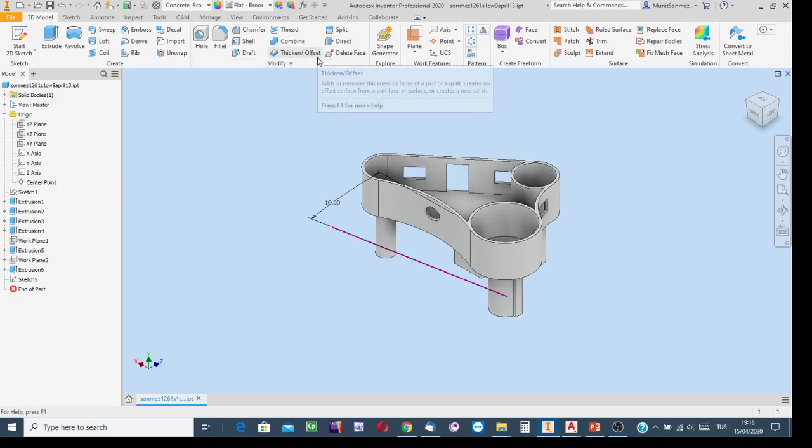But where is the work plane? Using this facility I couldn't have a suitable option because the direction of the opening is not perpendicular to this, not perpendicular to that, and I couldn't find a plane in the structure of the existing part of the object at present. Its orientation is perpendicular to the direction of the cutting. So that's why I'm going to create a work plane.